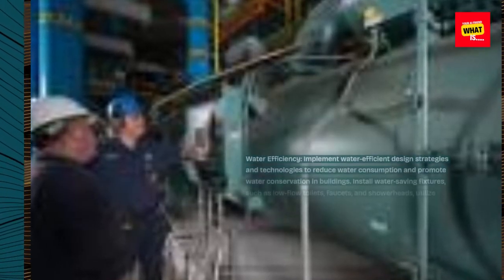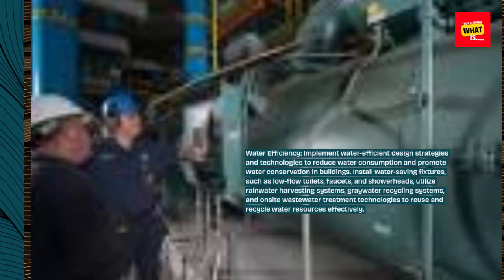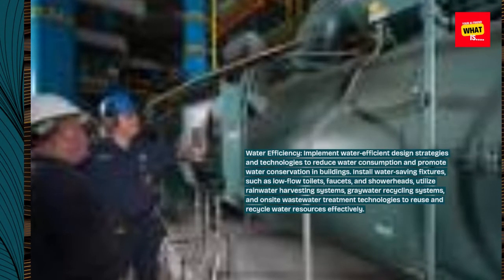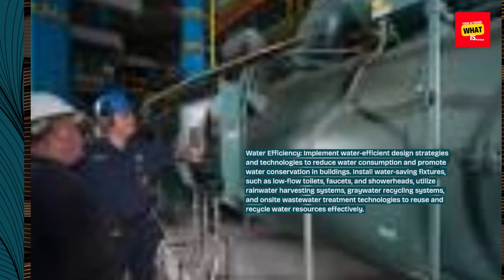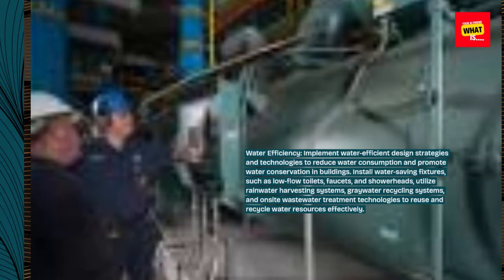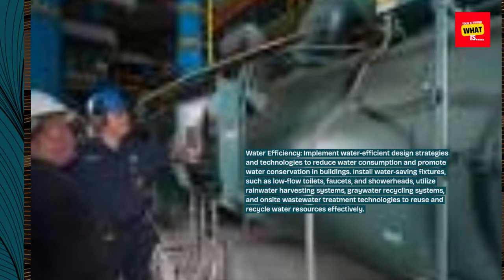Water efficiency. Implement water-efficient design strategies and technologies to reduce water consumption and promote water conservation in buildings. Install water-saving fixtures, such as low-flow toilets, faucets, and shower heads. Utilize rainwater harvesting systems, greywater recycling systems, and on-site wastewater treatment technologies to reuse and recycle water resources effectively.